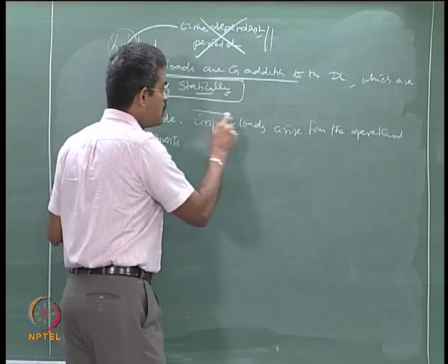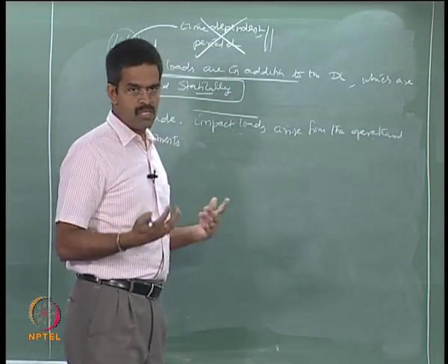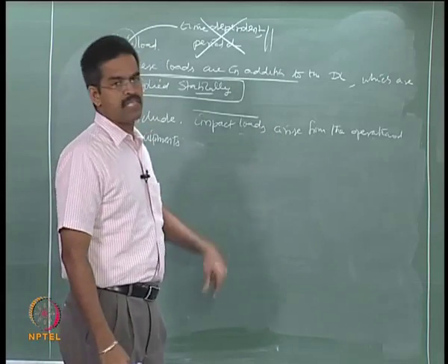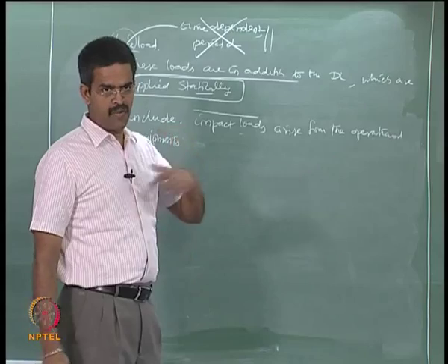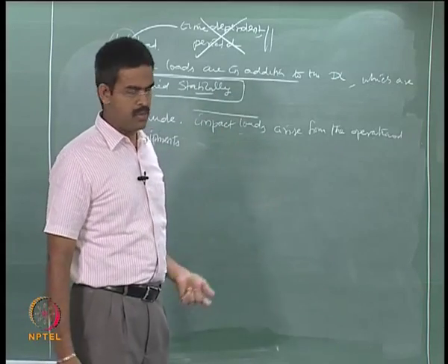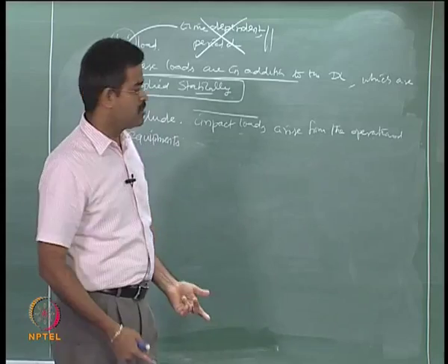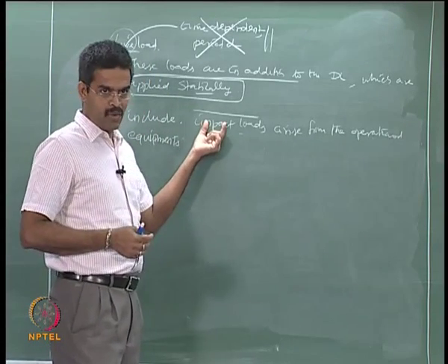These equipments have a rotary mechanism, because they are not static, they are running, they are working, like a generator, like a heat exchanger. They have compressors, compressors have rotors, they will keep on operating. So, the operational speed will impose certain dynamic effects on the platform where they are installed. So, we have to have an impact load.